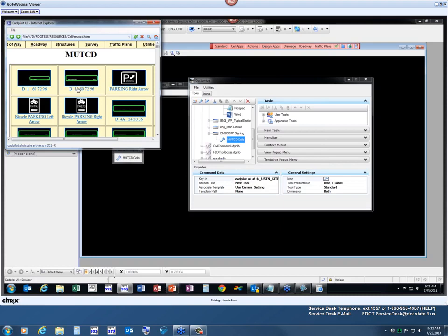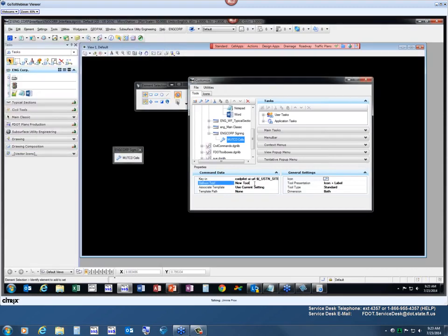You'll notice if I mouse over this and look in the status bar of the browser, it's going to go ahead and execute the command for CAD pilot to set the scale and attach the cell and then place the cell. So it has commands built in the web pages as well. Okay, so we've got that.